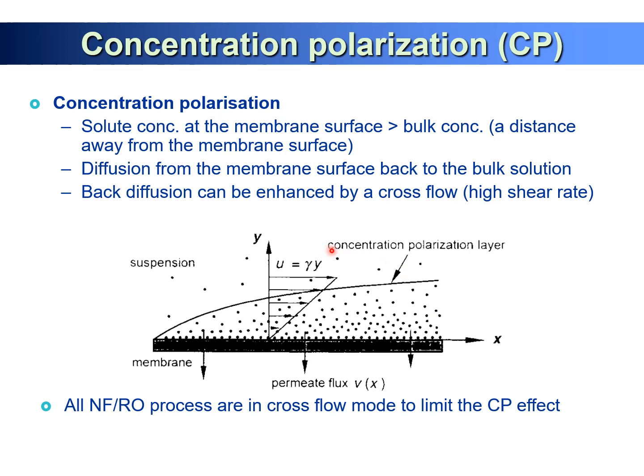So depending on your concentration polarization layer, your real osmotic pressure is different from the bulk osmotic pressure. So we also need to consider this concentration polarization to better design the osmotic pressure between the membrane feed side and permeate side.